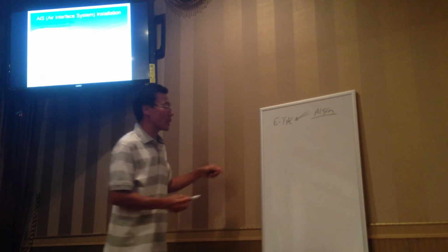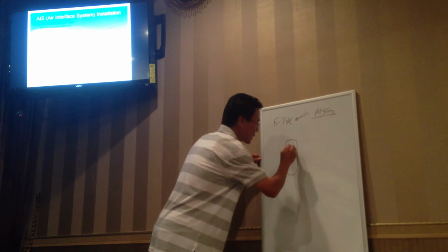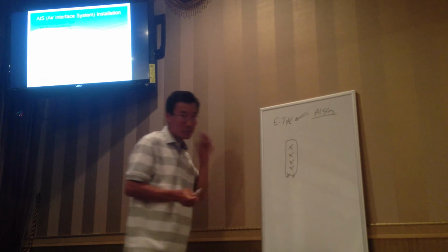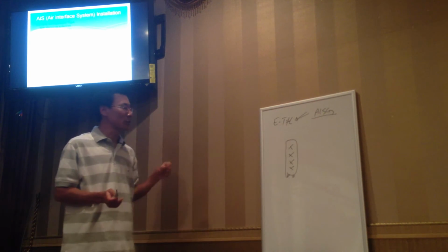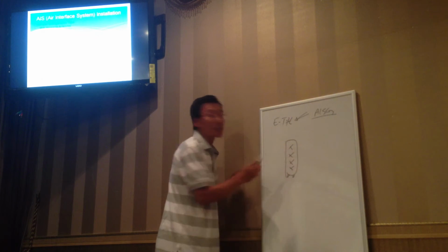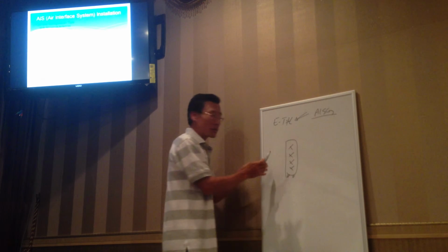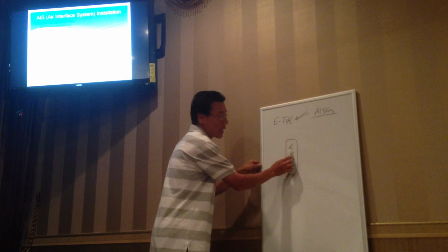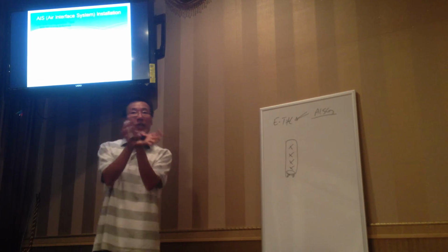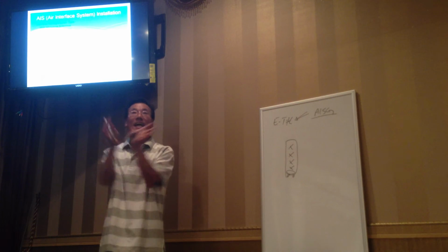The beam steering, how they came up with it, especially KMW. KMW is the first company to introduce beam steering, and still not many companies do. Beam steering is simply rotating. There are many ways to configure this. There's a motor, a stepping motor, rotating the whole antenna inside, not the outside.